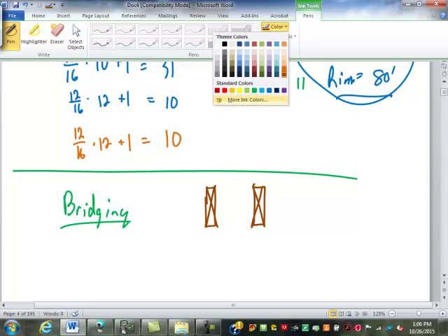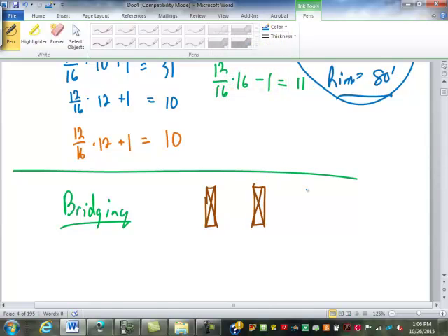There's actually a couple different types of bridging that can happen. There's something called a strong back. And a strong back is just blocking flat like that. That's usually not very effective, but that is how they do trusses. When you have regular floor trusses, there'll actually be a tag on the trusses where it says strong back. You actually run a 2x4 continuously through those, or sometimes they even call for just a 1x4. You have to nail it to the web of the truss at that location, and that causes them all to move together. But what bridging usually is, yeah, the X, like this.